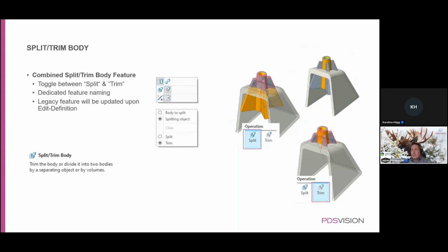This is particularly handy with multi-bodies. So if you are modeling, let's say, that kind of screw tower or whatever you call this thing, and you are also putting that, for example, as a library component and just throwing it in your model using UDFs, and now you just want to melt it into your existing geometry. What do you have to do? Previously, you used the solidify or some kind of offset replace approach for it. But today you can use the split or trim command for it.